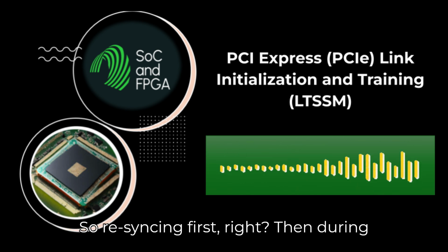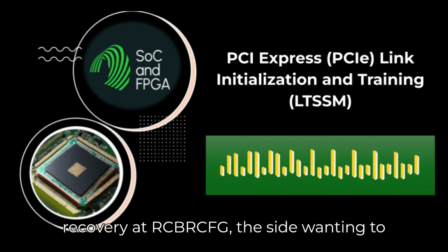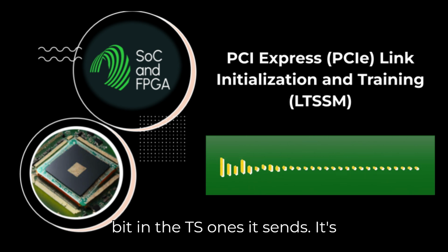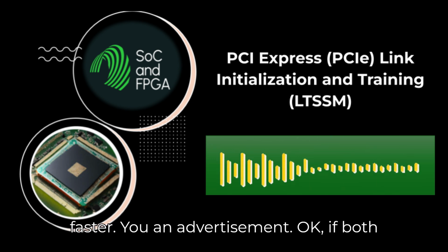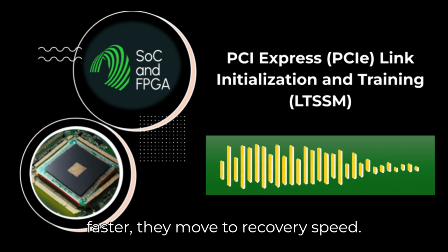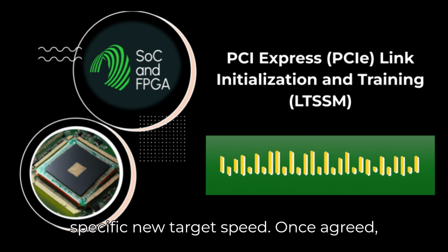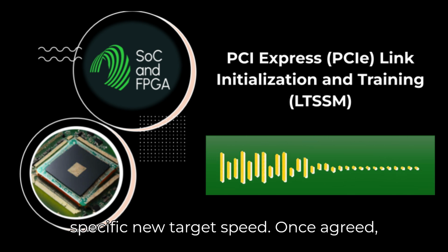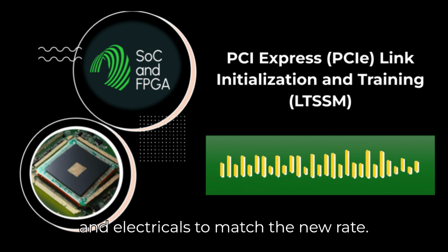So resyncing first. Right. Then, during Recovery.RcvrCfg, the side wanting to speed up will usually set a speed change bit in the TS1s it sends. It's basically advertising, hey, I can go faster. An advertisement. Okay. If both sides agree they can and want to go faster, they move to Recovery.Speed. Here, they negotiate and settle on the specific new target speed. Once agreed, the PHYs physically change their clocks and electricals to match the new rate.